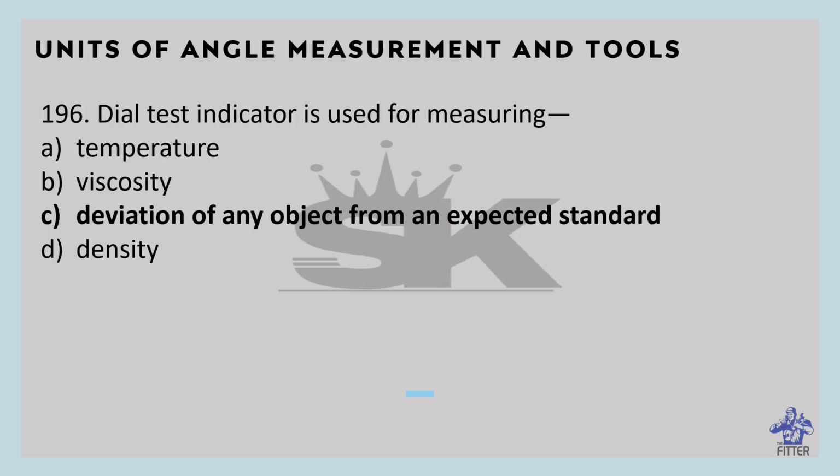And high magnification ratio is important in this instrument. A rotatable bevel is used in a dial test indicator for marking the final zero setting. And tolerance points are attached to the dial face for rapid checking of parts.